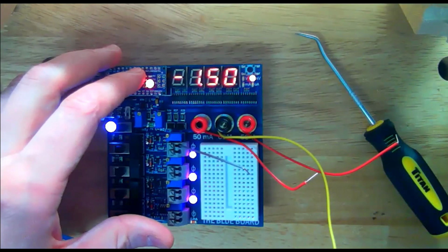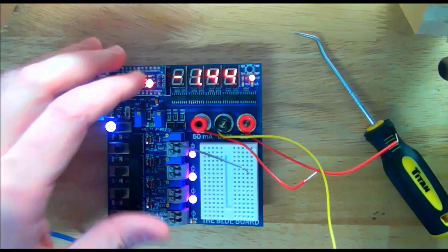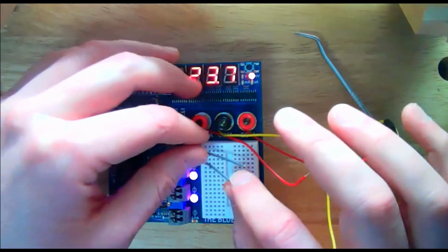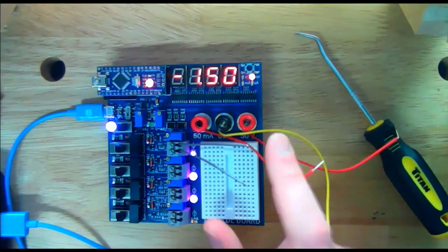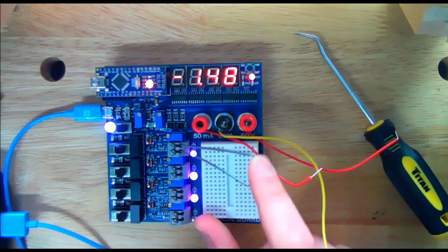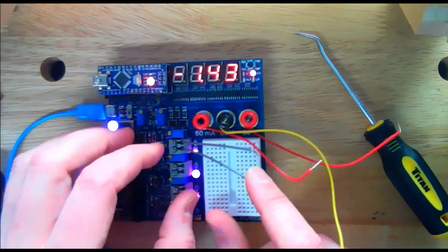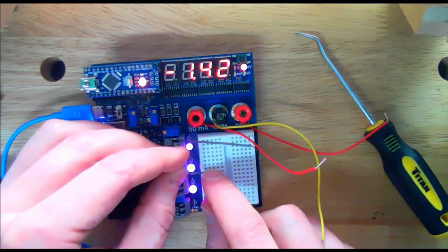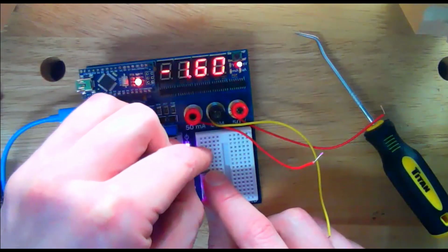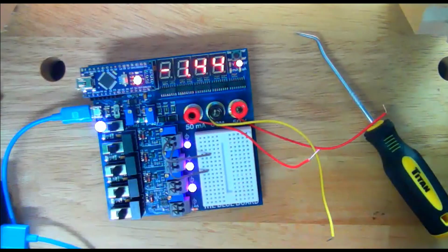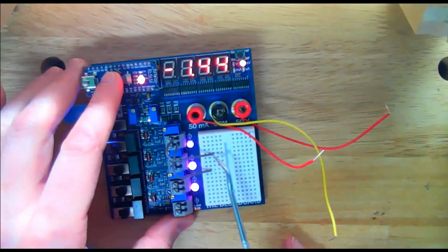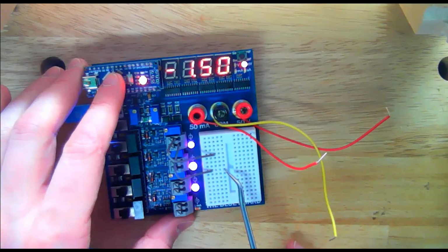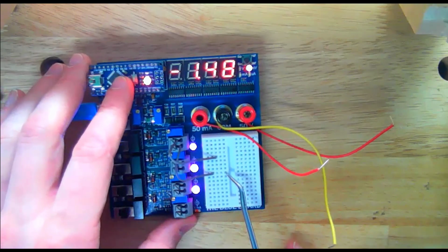Let's put another wire in here. Now I'm not being deliberate about my color coding here. Okay, but I've got 2 wires now. So I've got 1 wire connected to the top side of my 3-volt supply, 1 wire connected to the bottom side of my 3-volt supply. Just for safety's sake, I'm gonna connect these wires to 2 rows of my breadboard here. So I'm gonna connect this wire here to this row, and this wire here to this row. So now, this row of the breadboard is my positive 3 volts. This row is my negative terminal reference of my 3-volt supply. It's not ground though. There really is no ground in these boards. They're just floating supplies.